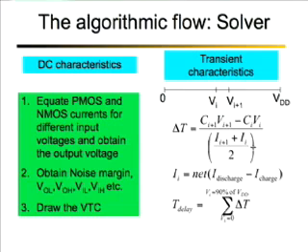In a time domain environment, essentially in a SPICE-like environment, one would try to solve the voltages at all different nodes of a circuit at a particular instance of time, and then would increase the time by a step of delta t, let's say, and evaluate again the voltages and currents at different nodes. So this is a time-based simulation that any traditional circuit tool would perform. But that essentially takes a long time, because in some cases we are looking at capacitors which are very large and currents which are very small. Since we do not know what kind of inputs we have to this tool, we wanted to make sure that we can always do a reasonable as well as fast estimate of delay and power.